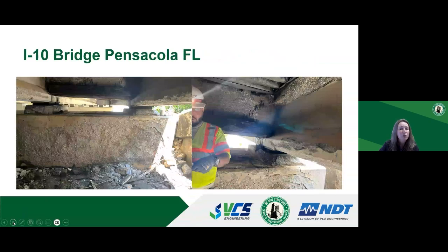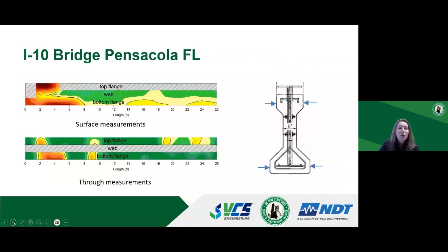This is another bridge fire example. This fire was significantly smaller. It occurred near the pier cap that you see there. It damaged the pier cap as well as 2 precast concrete beams and the diaphragm. Next slide, please. So here we couldn't extract the cores from the beams because of the very congested reinforcement.